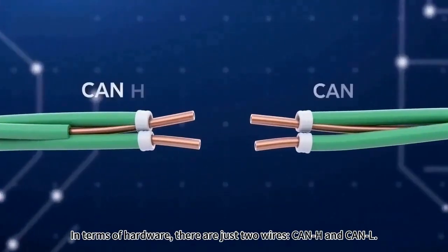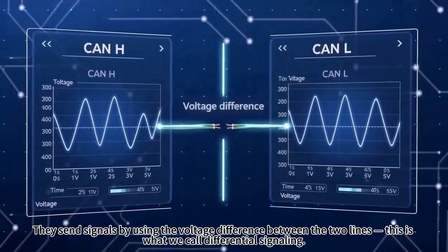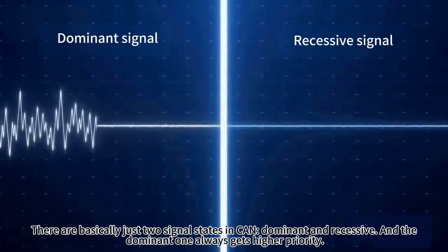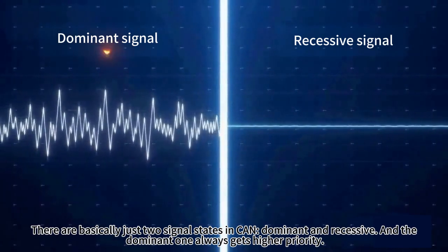In terms of hardware, there are just two wires, CAN H and CAN L. They send signals by using the voltage difference between the two lines. This is what we call differential signaling. There are basically just two signal states in CAN, dominant and recessive, and the dominant one always gets higher priority.